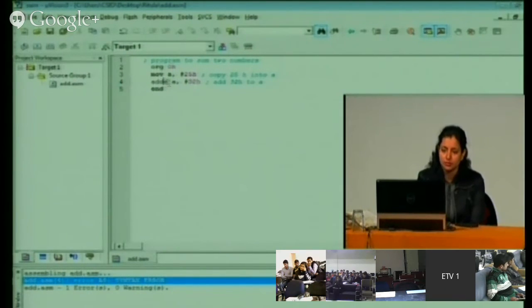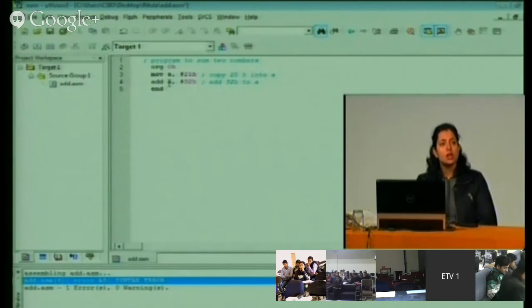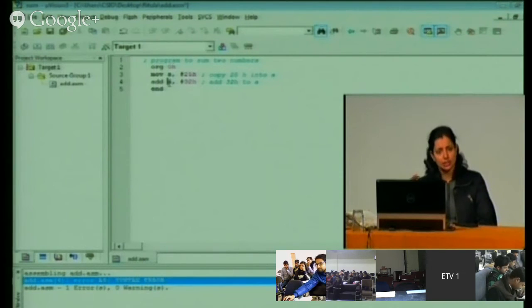What is the significance of warning? Okay, in case of warning, it doesn't matter. You may go ahead with your compilation, because a warning will mostly not be related to the hex file. It will be like, suppose I have not given the assembler directive org 0h or end, because in that case it anyways has to convert the hex file from the instructions.